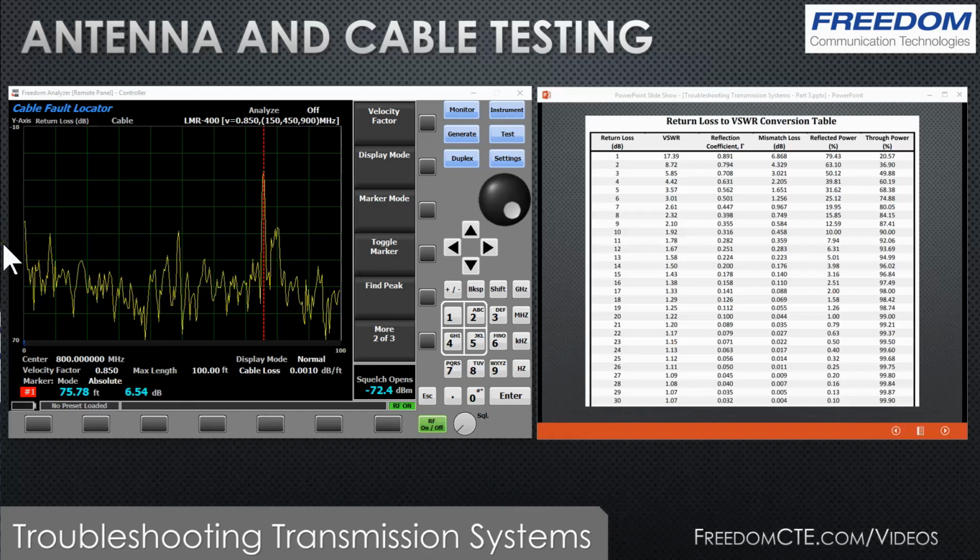So if I multiply 3.33 by 2, I get 6.66, and you can see we're getting 6.5, which is very close to the theoretical or specified amount. So there are no major flaws in this cable. Obviously there's an open circuit and the signal's not being radiated, but the cable itself is fine.